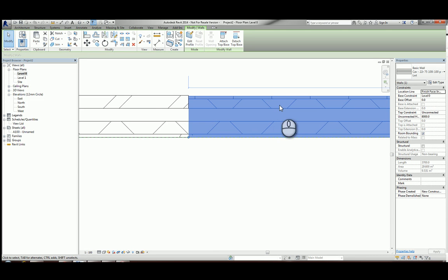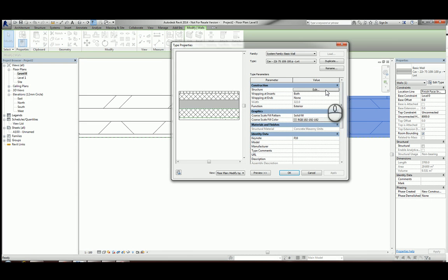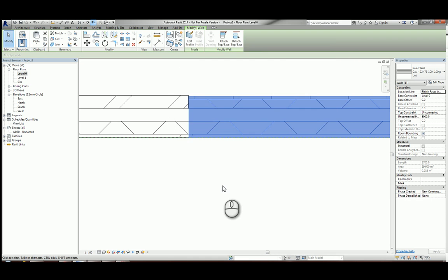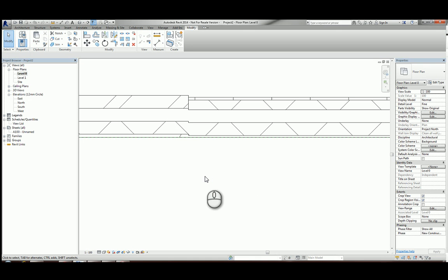I'm going to keep this one the same, but on this wall construction, I'm going to change my plasterboard thickness to 15mm. Watch what happens. Again we have the same problem. You don't really want that happening. Obviously, if it was happening to all of your walls at the same time, for all of your wall constructions, it will look right in plan, but it won't be right because all of your measurements, all of your setting out will all be changed. Like I said, very angry engineer.